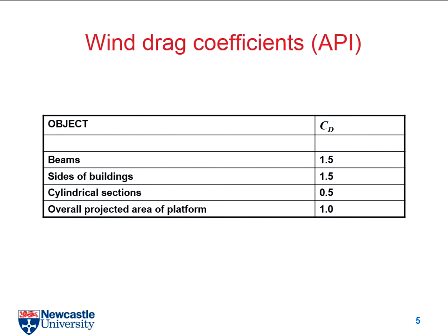But please remember that we can follow different rules. In our previous cases, we followed API rules, we followed ABS rules. Actually, we also have the rules from Lloyd's Register or CCS in China. After you finish the calculations by different rules, you may find that the results could be completely different. That's quite normal. At this stage we use a very simple estimation. But afterwards, if you carry out a CFD study for the same thing, probably you will have another result. And if you do a comparison, you will find that the result from CFD will be completely different from the estimations here. It's also quite normal.